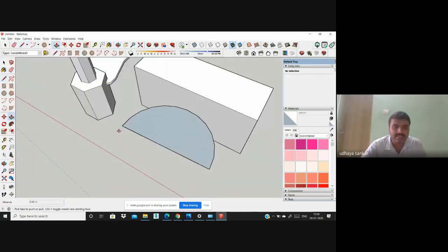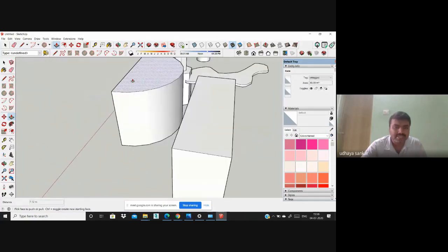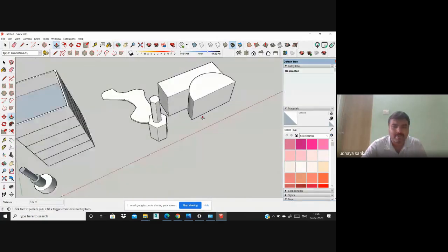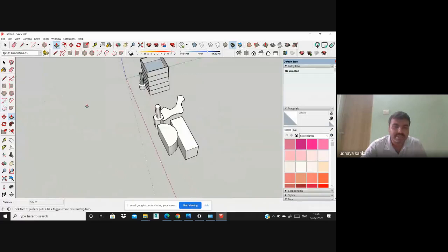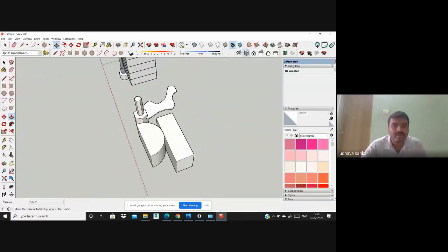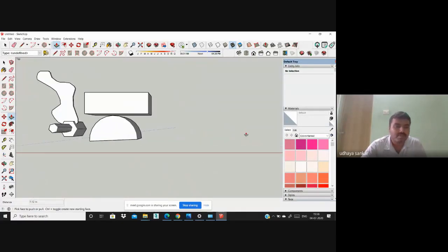Automatically it will be created. Simply go for push pull. Semi walls are this type of arc type of walls. Using this arc, it creates the arc type of walls, right? Simply go for the arc tool. So the first point, another one, I need this is a 3 meter, right?